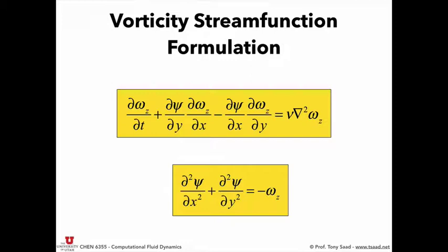What is the direction of vorticity? So du by dy is positive, okay? But then you multiply it by a negative sign, vorticity is going to go in. And that makes sense. If you take this arrow and that arrow, how are they going to rotate? This guy is going to push on the guy to the bottom, so it's going to make it spin. OK, so vorticity looks like this over here. That's an intuitive meaning of vorticity. So at boundaries, you generate vorticity. And this equation tells you how vorticity propagates into the domain. It's going to advect and also diffuse.